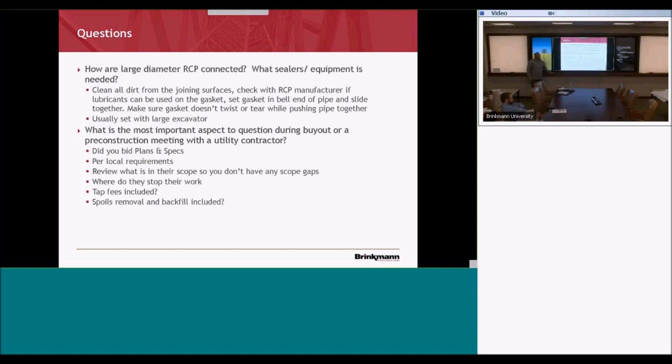This is technically included under the definition of plans and specs, but for the soils report, it's worth asking that specific question, because the soils report is what's going to dictate whether they can use rock backfill or dirt backfill. It's going to dictate what their compaction percentages need to be, and how they bench their trenches based on the soil type. There are all kinds of things that come into play in the soils report that a contractor could try to say, well, I didn't know it was going to be like that. And if you read the soils report, you should have known.